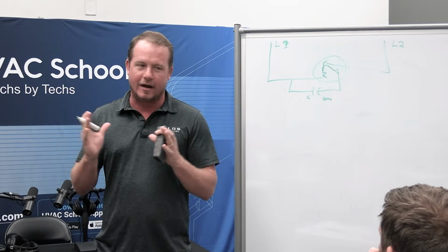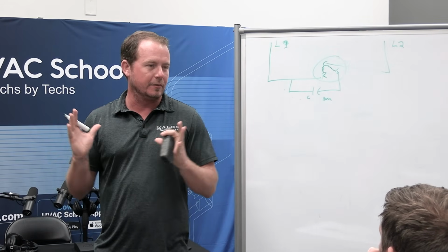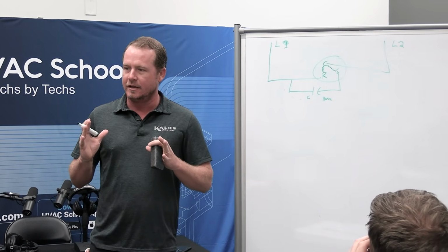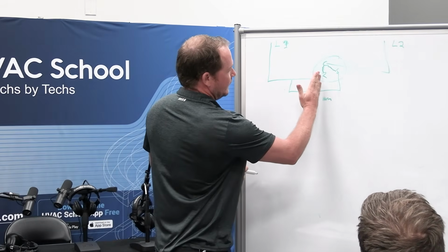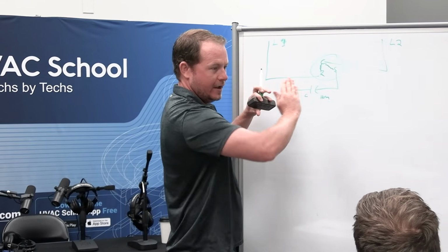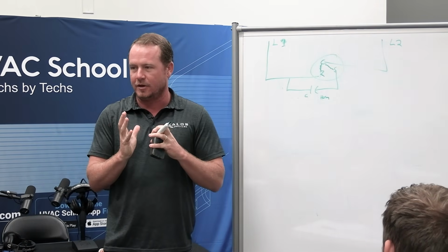And so as you pressurize, it kind of fills up, and then it maintains the pressure, so that way your pump doesn't have to keep cycling on and off all the time. It kind of has a balloon in it almost. You can kind of imagine a capacitor like that, or imagine that it has a membrane here, and it pressurizes and stores pressure and then releases it. So it's like a balloon storing pressure and then releasing pressure.